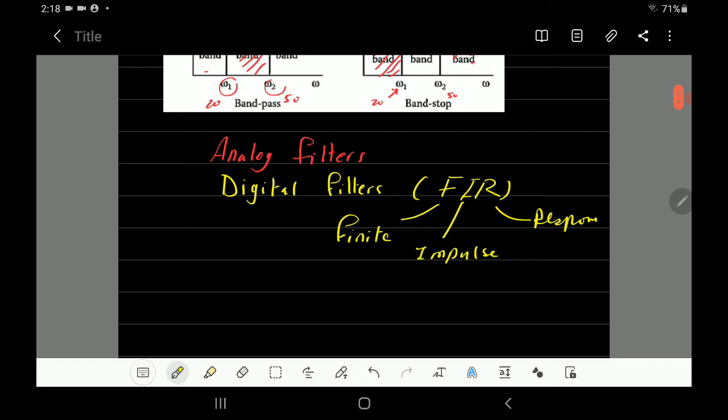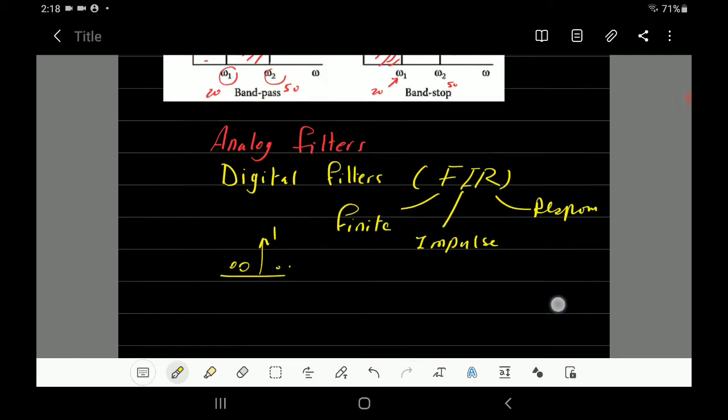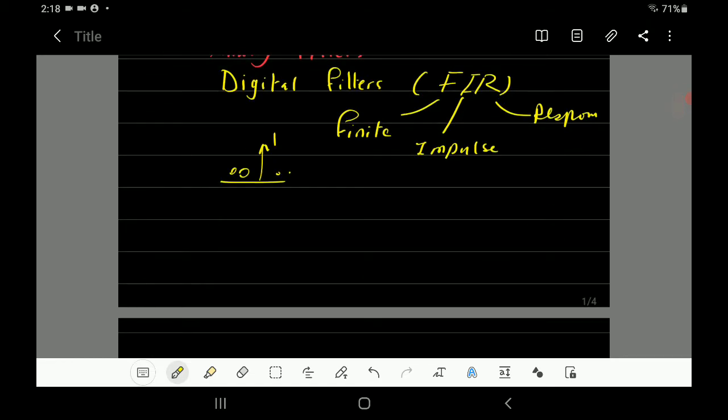So this type of filter, it means if you put in an impulse, that's a single one sample followed by many zero samples, the response will come out after the one sample has made its way through the delay line of the filter. A linear time filter consists of three building blocks only: additions, multiplication, and delays. The first one, addition, will look like that. It means if you have two signals, let's say x1 and x2, then you will get the sum.